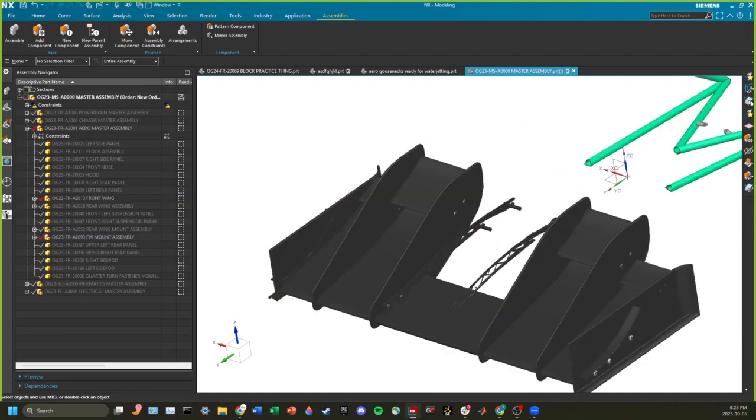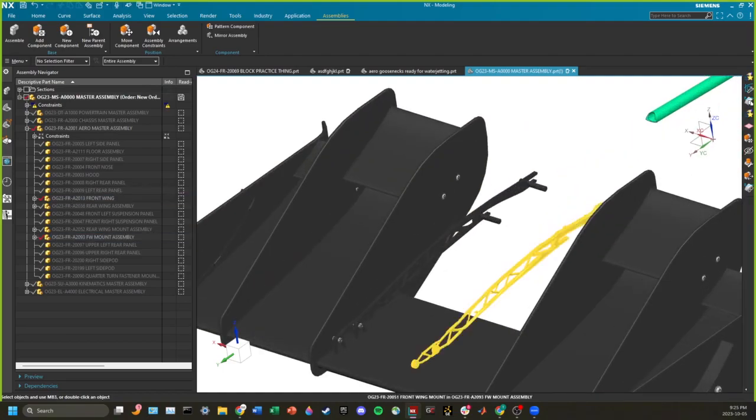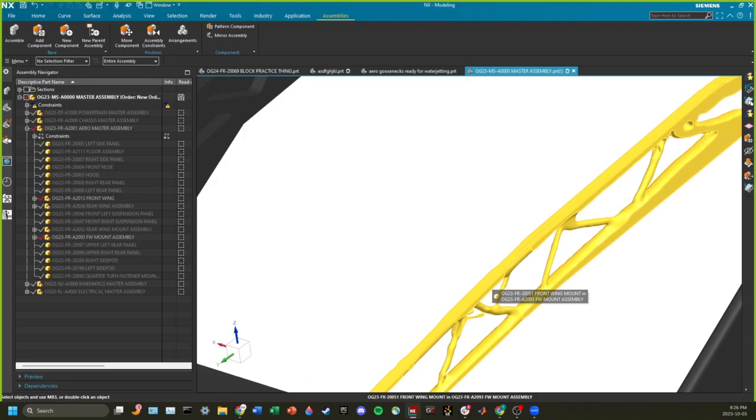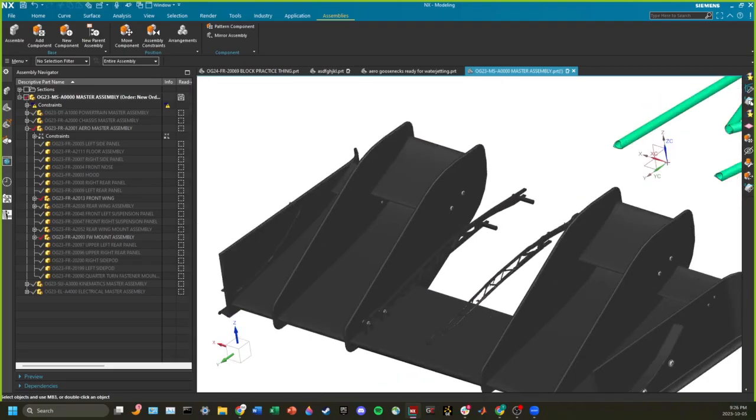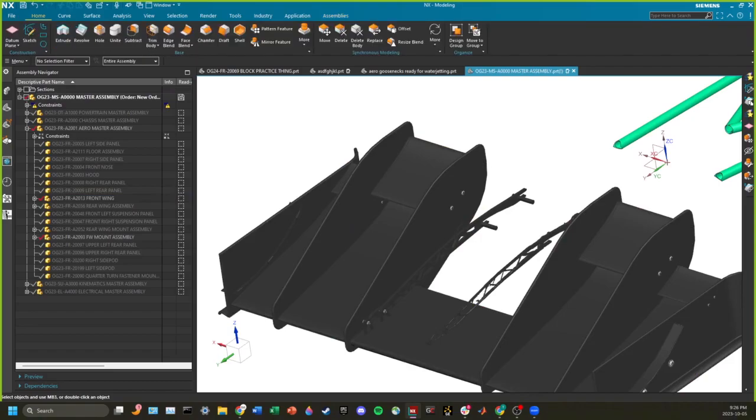The file I was trying to find was the goosenecks. Oh, this is the FEA version, where it was wave geometry linked to the hood to see how it would line up with the rest of the hood. So it just took the outer face of the part of the hood where it would be in contact, and then when people align it and stuff, it adjusts. It's quite smart actually, and you can find it under here.